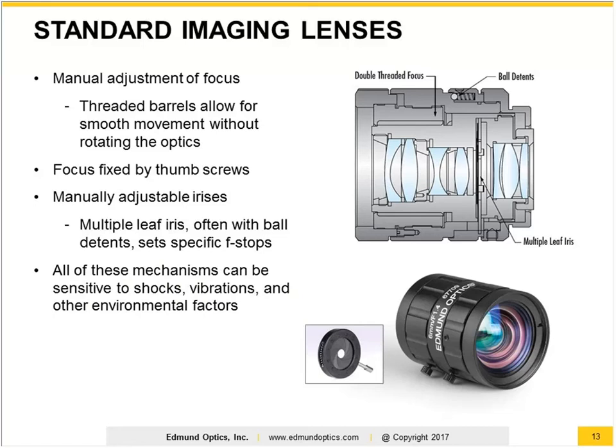The problem is that all these mechanics can have sensitivity to shock. If you bang them or drop them or whatever it may be, they're going to have a tendency to move. If they're in a high vibration environment, over time, things like set screws can loosen, or even simple shifts in place of all these mechanical mechanisms, if they come to rest or just adjust a little bit, can be a problem.